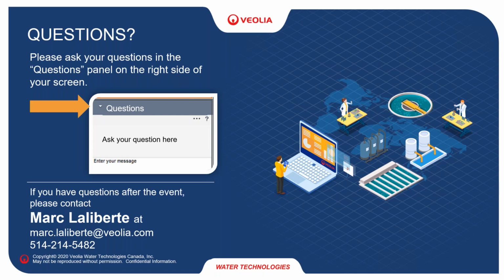So you've got a lot of sand in the water, and you will typically have 20,000 ppm of sand in the reactor itself, and that sand is used as the ballast. If the water coming in changes, say from 500 to 2,000 milligram per liter in TSS, compared to the 15 to 20,000, it doesn't really make much difference. So the ActiFlow actually is very resistant to changes in TSS.